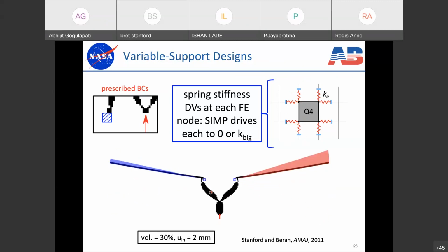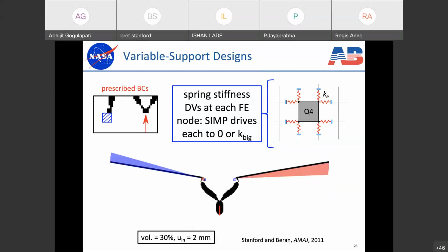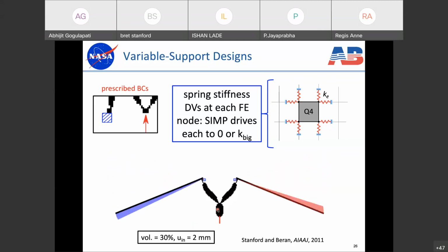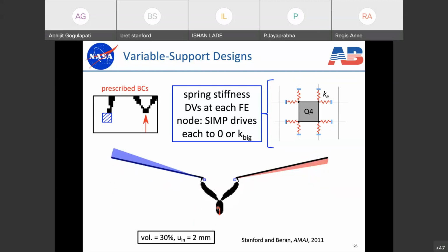When we do that, the boundary conditions are moved from the lower corners here, which is where they used to live, up to this location really close to the wing joint, and we have a substantially simpler wing topology than we had previously. So this really worked quite well. So this is all 2-dimensional topology optimization.